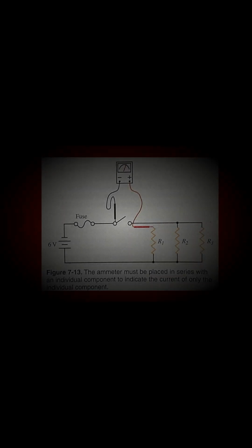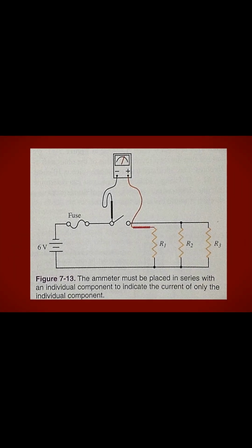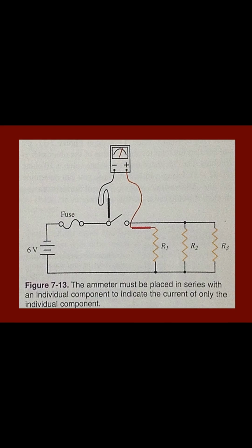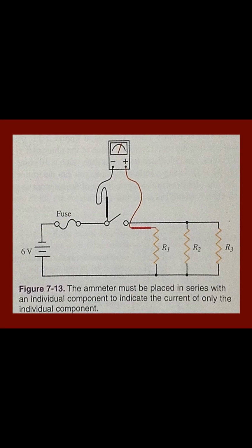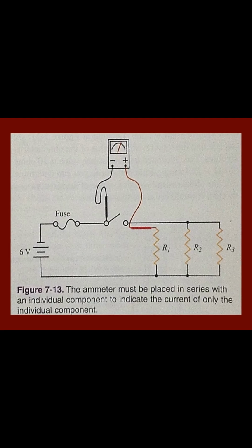In figure 7-13, troubleshooting a parallel circuit will become easier as we learn more about the current, voltage, and resistance characteristics. One factor that assists us in determining the best method of troubleshooting a circuit is determining how the circuit has been assembled. When a breadboard is used to construct circuits, troubleshooting is much easier than when the components are soldered in place and we must first desolder to take the readings.